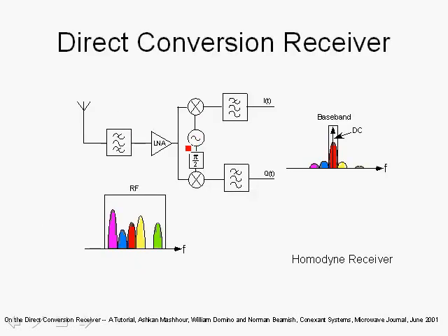If we go back to the direct conversion receiver architecture, typically you have very high gain stages in the baseband, versus the case in a heterodyne where you have a high gain prior to demodulation back to baseband. And therefore any DC generated due to self-mixing would go through amplification in the baseband and cause a large DC component at the input of the analog to digital converters. And this DC offset has to be estimated and compensated for by the baseband digital signal processing and fed back to the analog front end and eliminated.